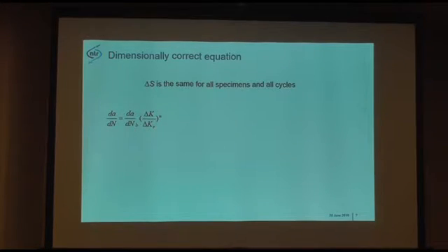So if you do multiple tests with the same stress range, and you substitute the n for 2m, then you can rewrite this to an equation like this. So the stress is out, and we make this just an equation from the crack length. In the next slides, I will plot everything against the crack length. This is the only variable in there, and it's also in beta squared, so there's also a crack length dependence in that.